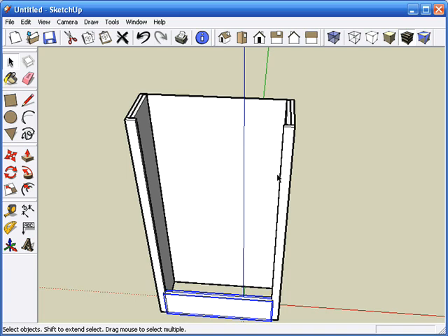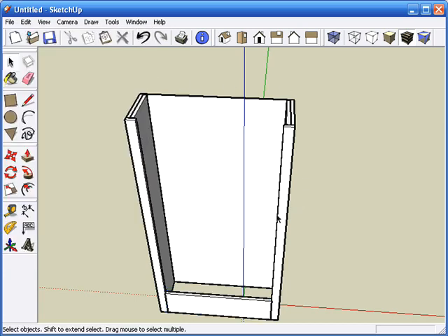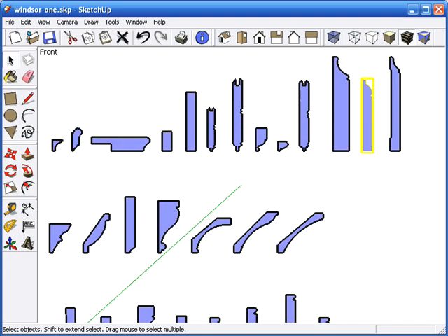I'm going to open up a drawing that I have. Actually, I already have it open. Let me just switch to that drawing. Here it is. This is a collection of moldings that I borrowed that's available on my website. It's Windsor One's Moldings. And I'm going to take their crown molding from the Greek Revival style, this piece right here. I left-clicked it until it's selected, and then I hold down the Control key and hit the C key for copy. So it's Control C to copy something.